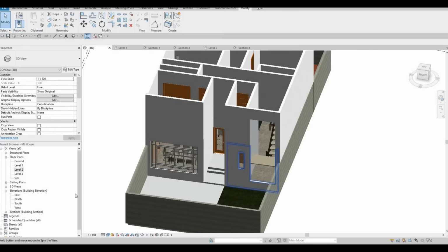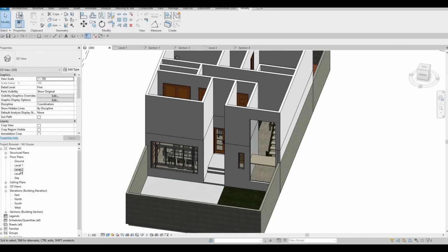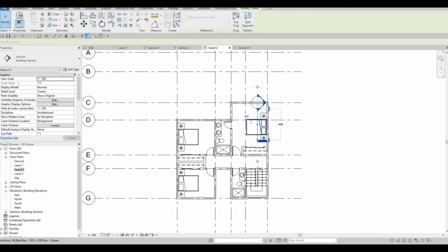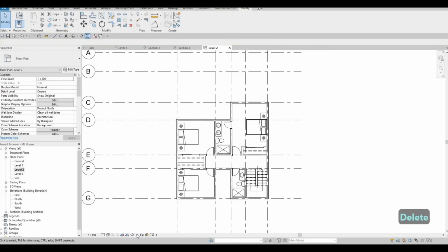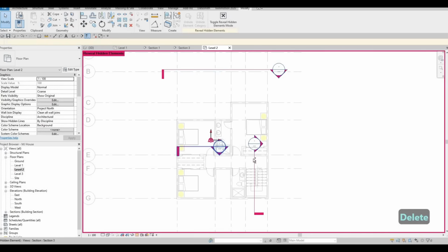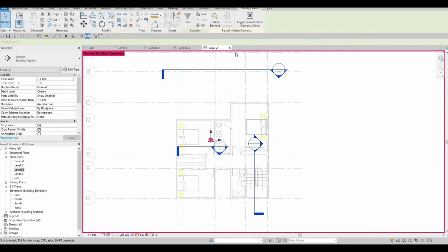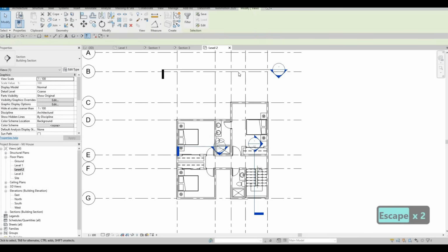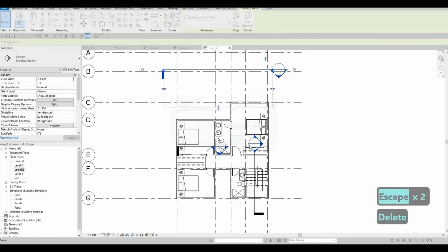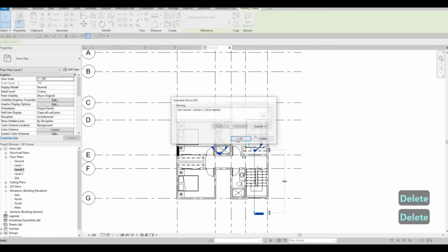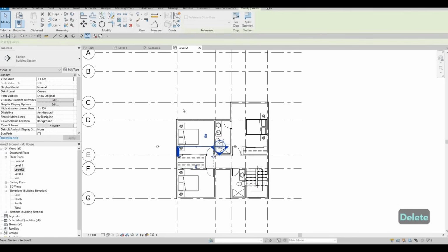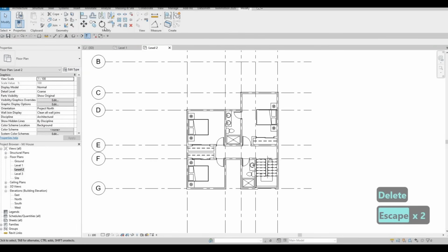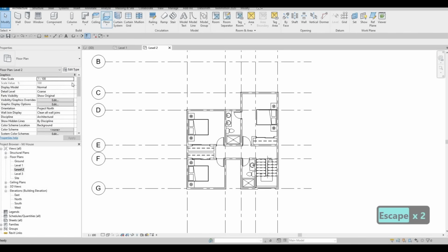And then after that, what we could do is we could place the floor. So here I'm just going to delete this for now. I'm also going to unhide all of this because we don't need it anymore. And I just remembered, I'd rather delete it than hide it. And then let's go to architecture, click on floor.